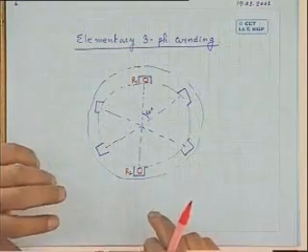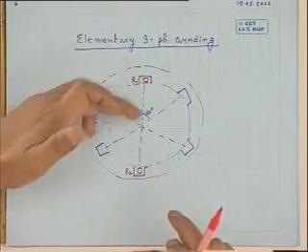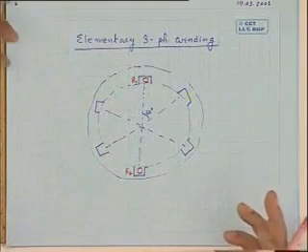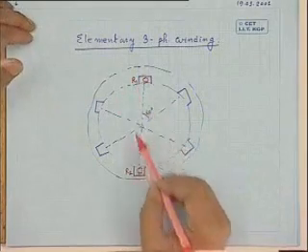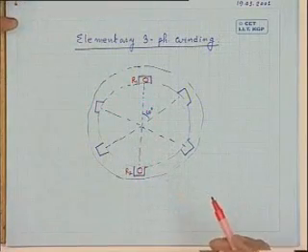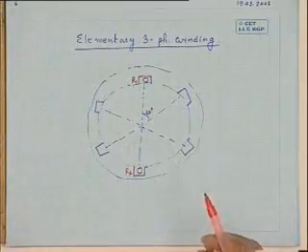And are we making the windings 2-pole or any other pole? Certainly a 2-pole machine, because once I have chosen the coil span equal to 180 degrees mechanical, 180 degrees electrical is always correct, but it is diametrically opposite. It means it will be a 2-pole construction. Why 2-pole?